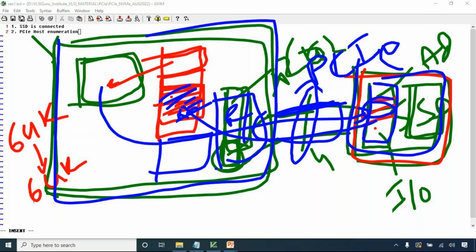In PCI Express there are four types of commands, four types of TLPs. One is configuration write and configuration read. Second is memory write and memory read. Third is IO write and IO read. The fourth one is messages, used for generating interrupts, broadcast messages or low power messages. IO write and read won't come into the picture because they were mostly targeted at legacy PCI Express based devices, where we wanted to support the PCI capability. When I get into the presentation, you will understand more about those aspects.